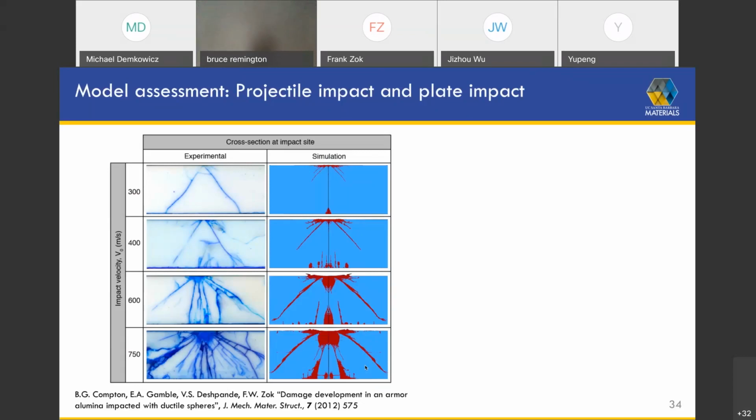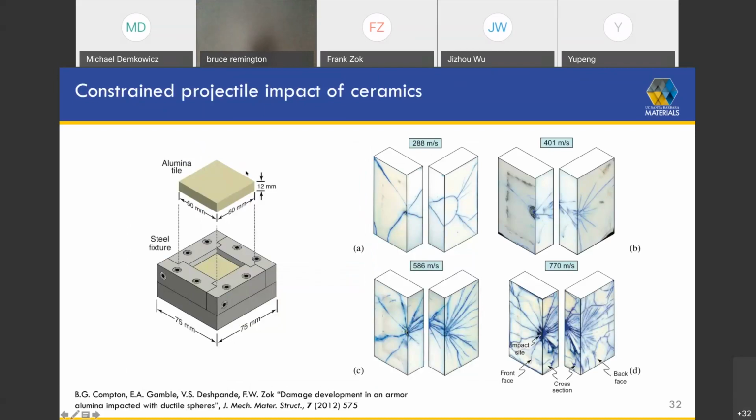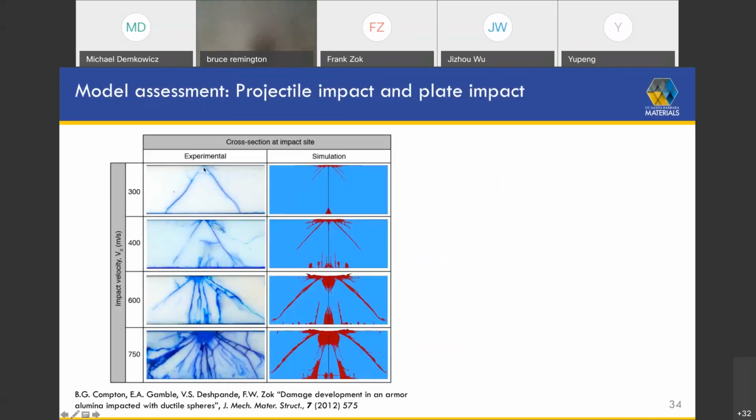What you find is that when you have a point load of the type that you might imagine hit this point here, there is a critical force that's needed to create these so-called cone cracks. And there's another paper on this where we've actually done analyses of the forces that are present at the contact site, and in particular, the maximum force that's obtained, and used that to predict the onset of cone cracking.